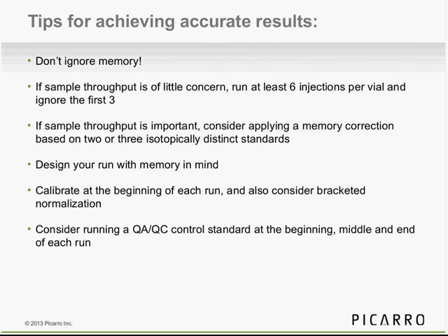Okay, so tips for achieving accurate results. I'd say the most important thing is don't ignore memory. It's something that you need to be aware of if you're running this instrument. And I certainly think you want to either do multiple injections and ignore the first few, or you should correct for that memory effect.